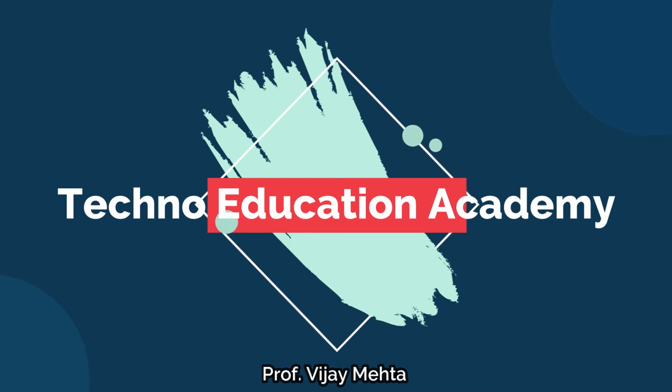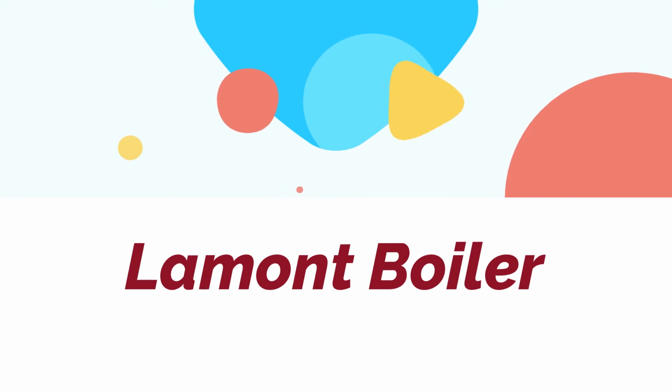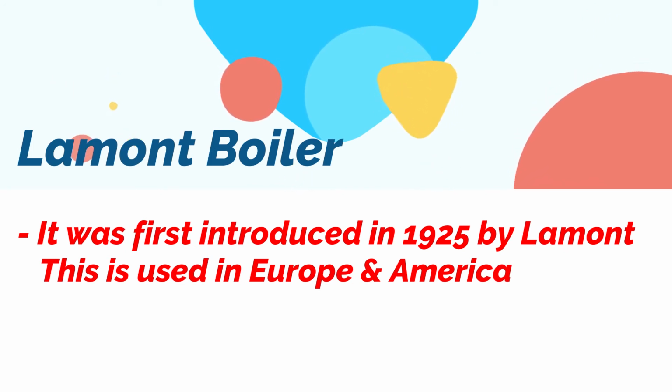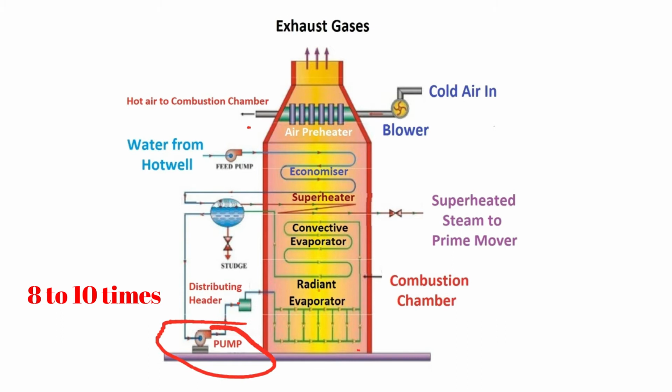In this video lecture, we will discuss one of the high pressure boilers, the Lamont boiler. A forced circulation boiler was first introduced in 1925 by Lamont. This is generally used in Europe and America. A centrifugal pump circulates water equal to 8 to 10 times the weight of steam evaporated. This water is circulated through the evaporator tubes.